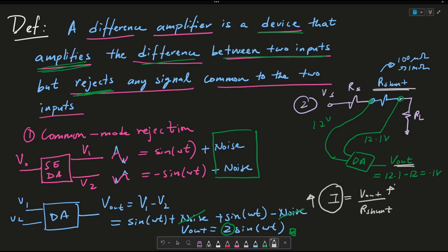Then depending on my voltage, we can say that if the voltage goes above, let's say 0.5 volts, we trigger some type of short that brings it to ground or turns off my power. But essentially, the basic idea in our electronics is that this is how we can use the difference amplifier to measure current. I hope these two examples make sense and clarify the reasons why we might need the difference amplifier.